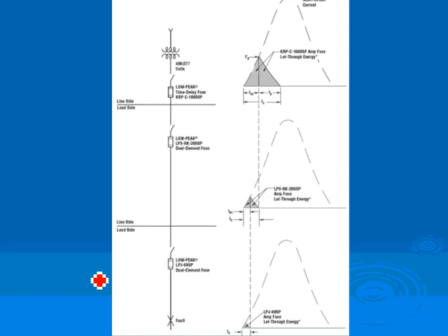So the heat generated will bake your switch gear. You're getting tons of heat there. You're baking that piece of equipment. Okay, that's the heat generated from the short circuit. Also, the short circuit will generate magnetic force that shakes that switch gear. So you have a piece of equipment that's being shaken and baked by this current. How much shaking and baking will depend on how fast Mr. Fuse or circuit breaker will trip.